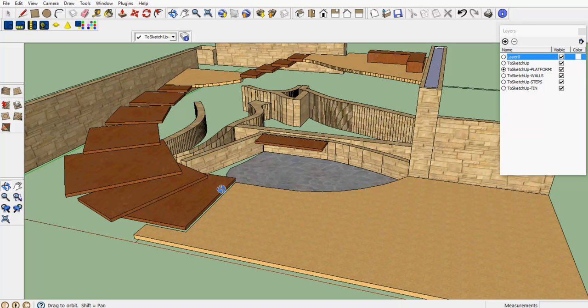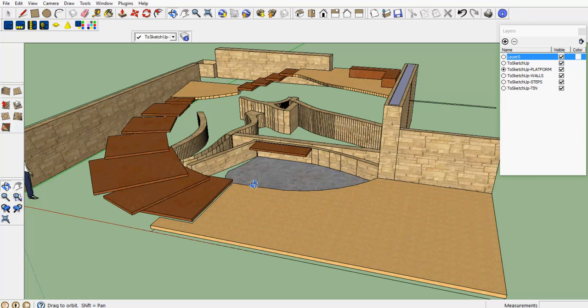Well, here the model is in SketchUp and we're now applying some textures to surfaces in the model. I guess because this is a very steeply sloping courtyard with a couple of meters drop from the top platform down to the bottom, the next step might be to try and construct some sort of terrain model, and we can apply either an earthy texture to it or maybe even a ground cover texture to it to improve the look and feel of this model when we finally render it.